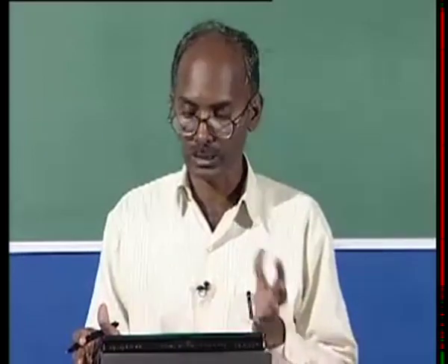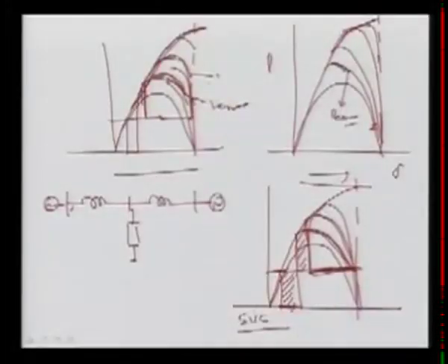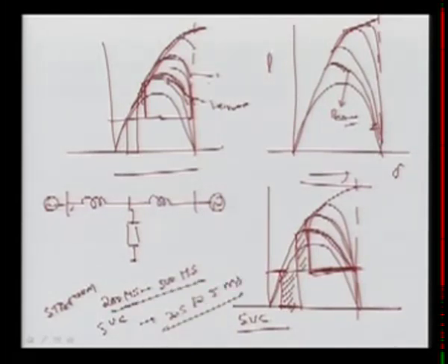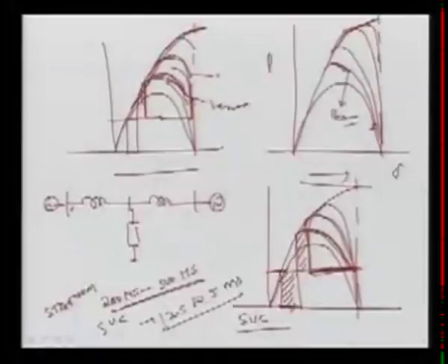It's very simple to control, very simple to manage, and already we are having all these things. If you see the time response here, the STATCOM time response is from 200 microseconds to 500 microseconds. However, for SVC it is from 2.5 to 5 milliseconds. So the STATCOM is very fast compared to the SVC as well, because we are having the control, the converter based technology. Here we have inductors. If you are switching here, you will require some time. So here this time is milliseconds, so it is also very fast as well.